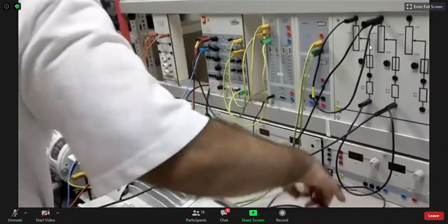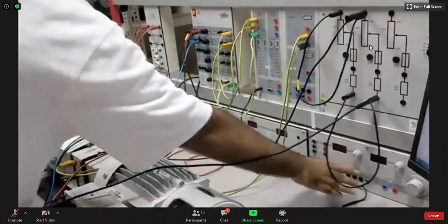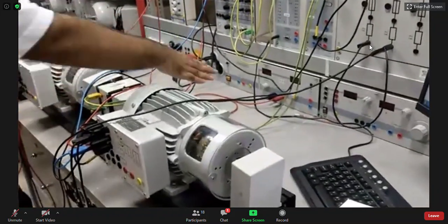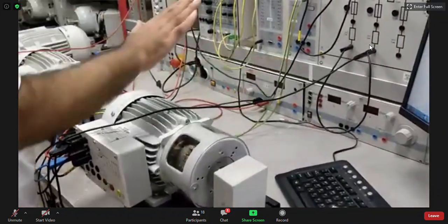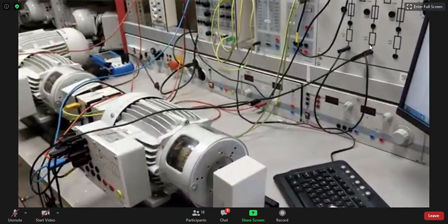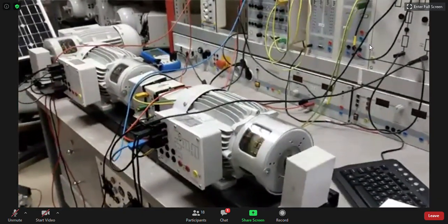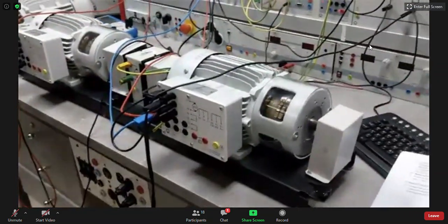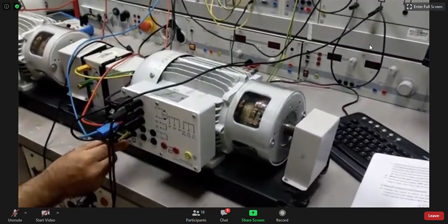Now I am disconnecting the power supply. That's it. We don't have a power supply for the field windings, isn't it, guys? This is for the motor, we don't care about this. But for the generator now it will excite itself. So now, as we said before, E1 will go where? E1 will go to C1, or to the load, isn't it?